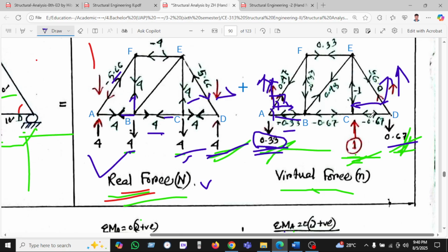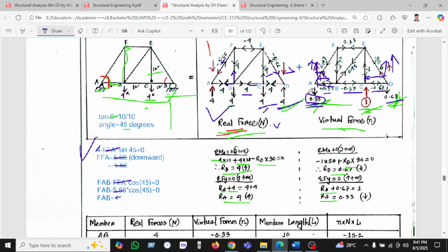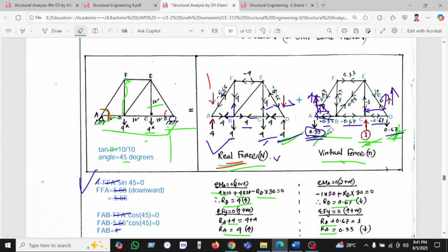If we calculate the horizontal member, then we will find 0.67 in this figure. So 0.67 is going in direction D, joint D. So joint C will be in the opposite direction. When C to D is opposite, then CB will be opposite also. So all these things we can calculate in the same way. I'm just skipping here. I hope that you can calculate all things as in SM1 of Solid Mechanics 1, or the basic equilibrium formula.